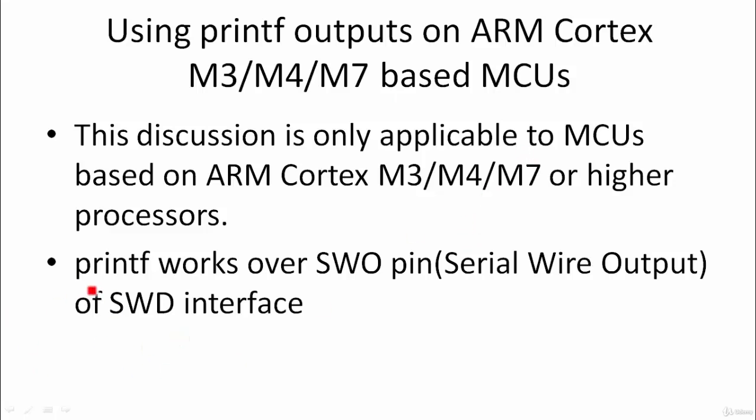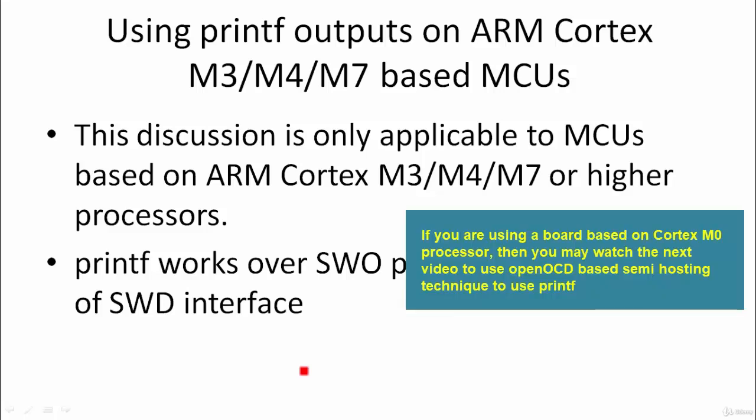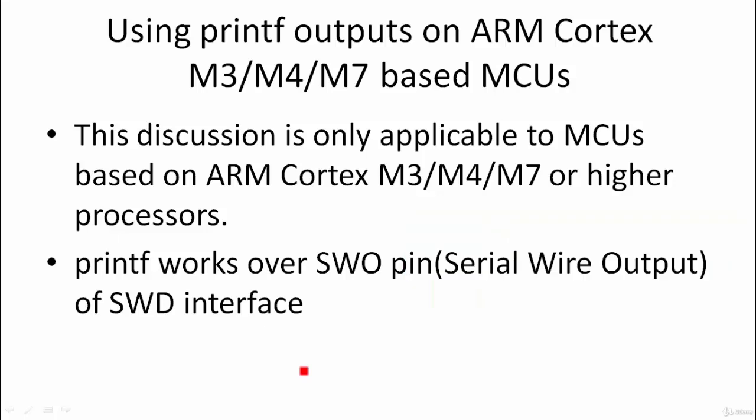This discussion is only applicable to microcontrollers based on ARM Cortex M3 or higher processors. It will not be applicable to ARM Cortex M0 or M0 plus processors, because in that case you will not be able to use the ARM Cortex processor's trace functionality, which we are going to discuss in a moment.